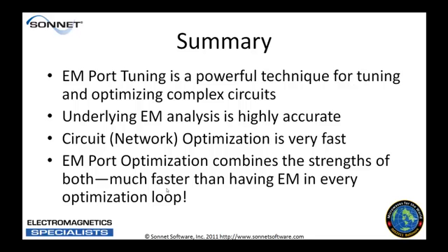EM port tuning is a powerful technique, as we've seen, for tuning and optimizing MMIC matching circuits and a variety of other circuits. It uses underlying EM analysis, which is highly accurate, but it leverages circuit optimization, which is very, very fast. So we're using the strengths of both approaches: the electromagnetic simulation for accuracy, the circuit theory optimization for speed. It is a lot faster than having electromagnetics involved in every turn of the optimization loop, and it has the added benefit that the designer, you, are learning a lot more about your circuit.